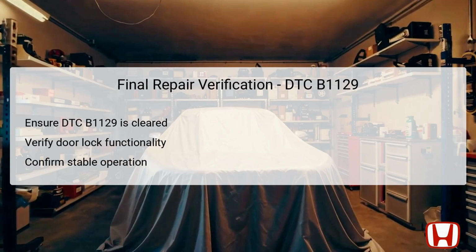After completing all necessary repairs as per the outlined troubleshooting steps, it is vital to conduct a final verification of the repairs. Start by ensuring that DTC B1129 is cleared from the system using the HDS. Next, confirm the door lock functionality using the driver's door lock knob switch several times to ensure locking and unlocking occurs without issue. Observe the behavior of the vehicle's locks, ensuring they operate smoothly and consistently.